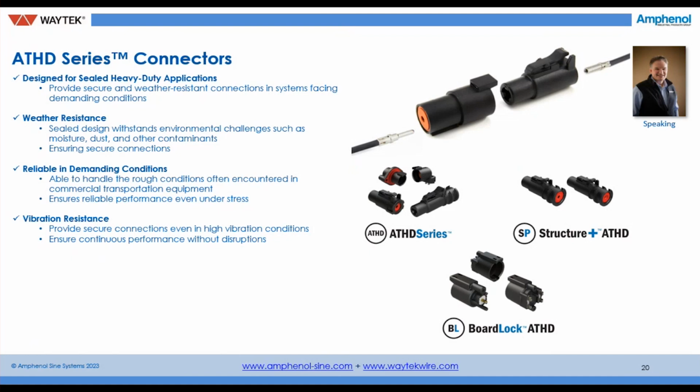And then once again, we've got that Structure Plus built into our ATHD, that if you do want to put that shrink on the back of it or do an overmolding, this is certainly capable. But I really want to speak to here, notice the silicone sealing. You can see it in the rear of these connectors. You can also find it in the front, or it's hard to view from this particular angle. But sealing IP68, IP69K sealing on all of these connector series is really a must.